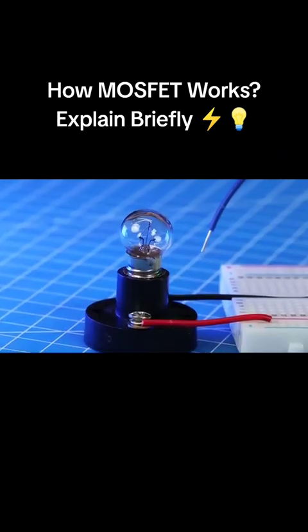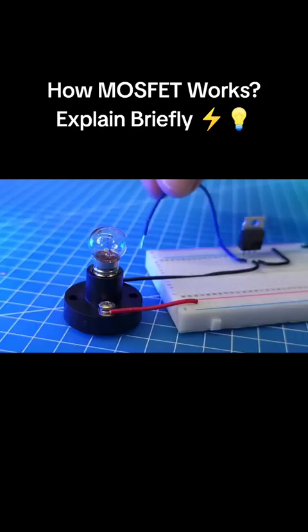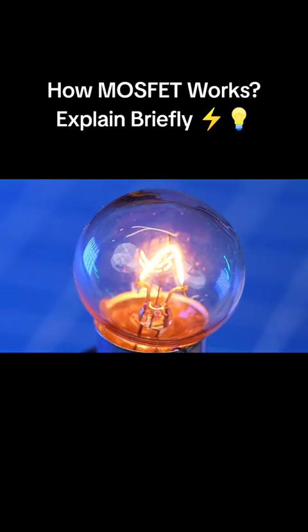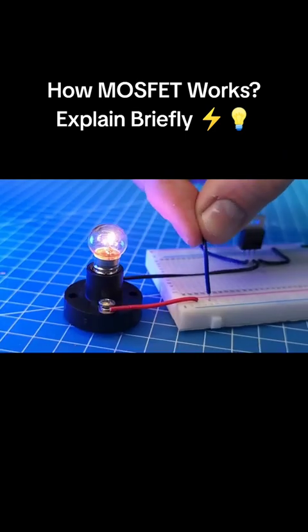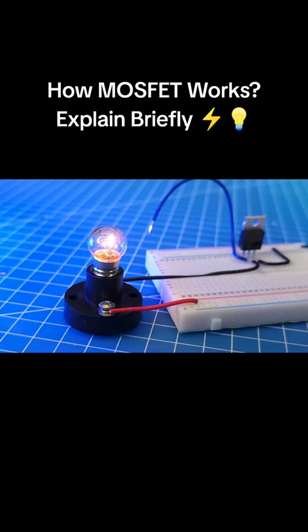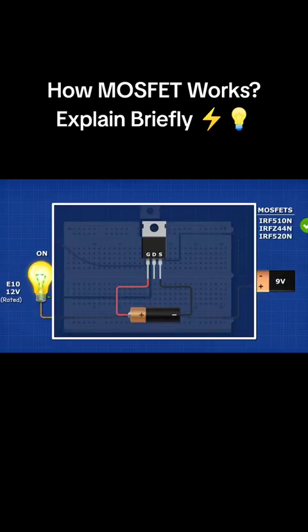Notice that the lamp is off, but if we connect the gate wire to the 9-volt supply, it will activate the Mosfet and the lamp turns on. Current is flowing through the circuit like this. Now, if we disconnect the voltage to the gate pin, the lamp remains on, and that's because the Mosfet is now stuck. The gate terminal acts like a capacitor and it stores charge. If this charge has nowhere to go, then the Mosfet will remain activated.